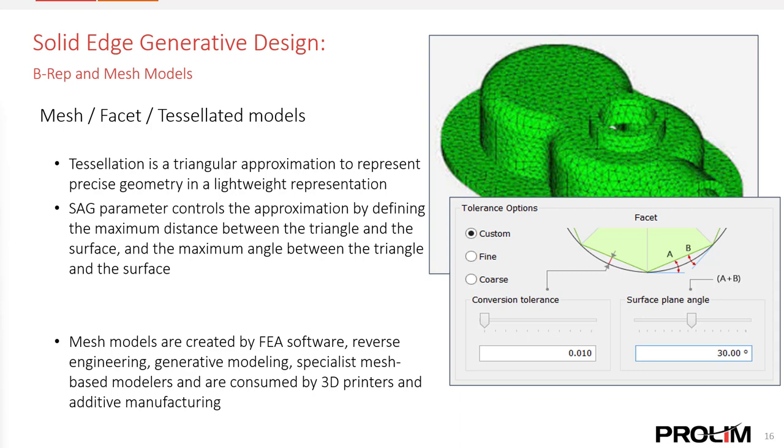In fact, Solid Edge now supports convergent hybrid modeling, which gives the user the ability to model directly onto a true mesh or faceted body, speeding up the design time by eliminating the need to convert the mesh body to a BREP body just to add modeling features to the design.